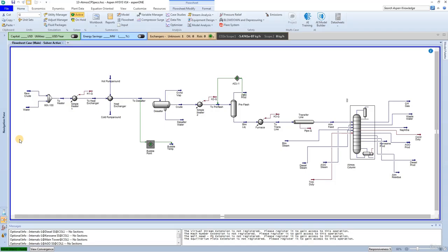Task 1. Add the vacuum tower. Atmospheric distillation of raw crude is typically temperature limited to conditions below 360 degrees centigrade to 380 degrees centigrade. At higher temperatures, the crude could thermally crack and form equipment-clogging petroleum coke. As a result, a significant amount of heavy hydrocarbon resid is produced from the atmospheric column, which requires further processing.